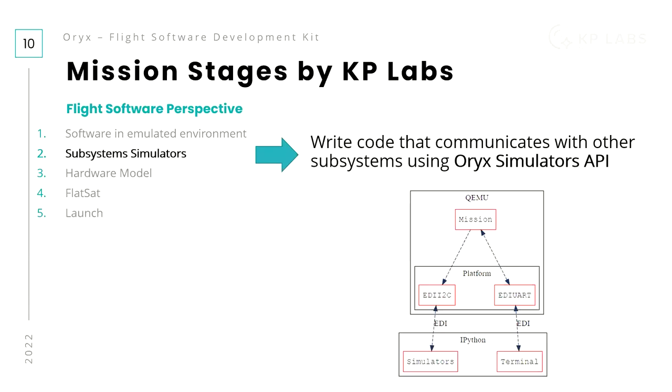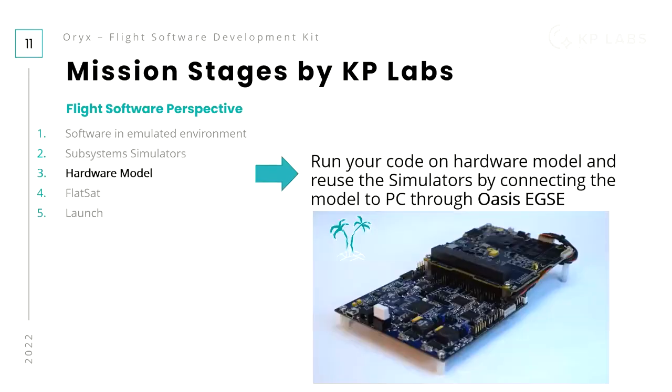However, it makes no sense to do this without also running it on actual hardware. So that's the next step, running it on actual hardware. You take your code, the logic part I've shown on the previous slide, and you exchange the drivers for physical drivers. So now you say, okay, I2C, you are actually an I2C, you will drive some pins on the microcontroller when asked for read or write.